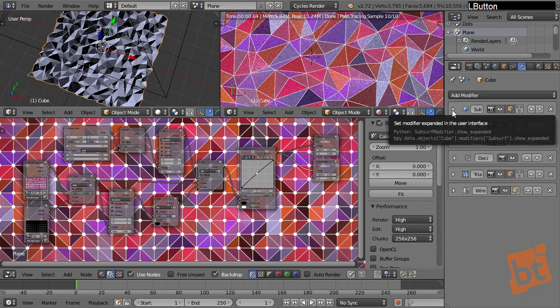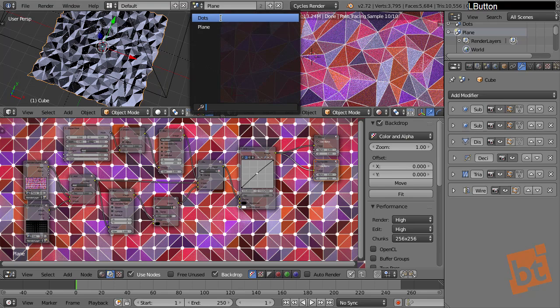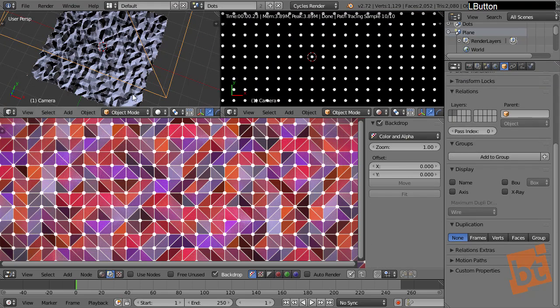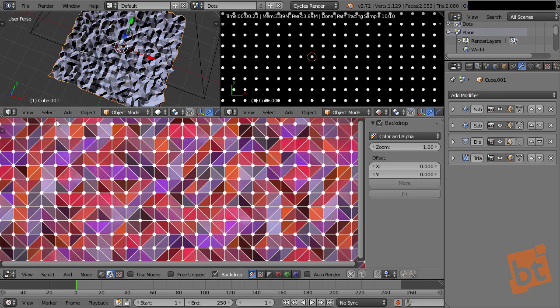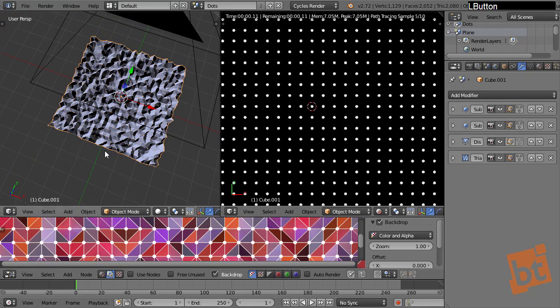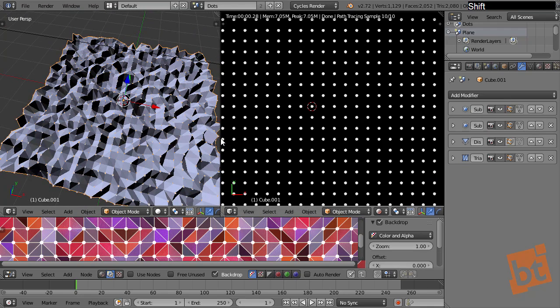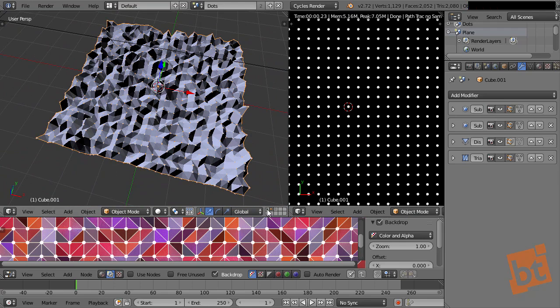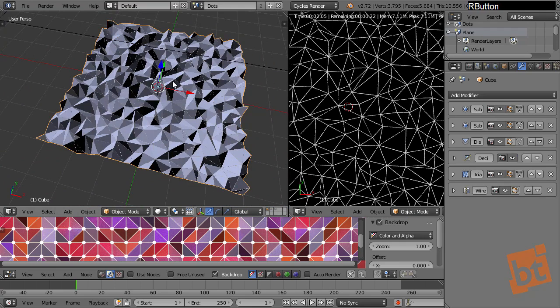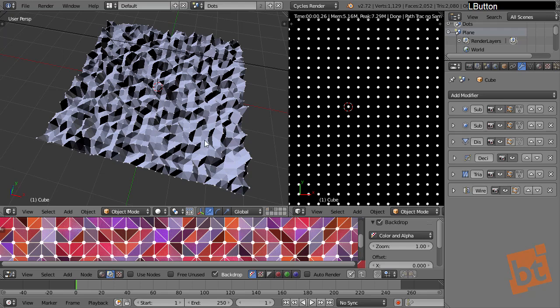And another cool thing here. Let's say we have that, and now I'm going to show you the other thing. As you can see, this is not working. The dots are not in their position. The reason is that this mesh is not taking into account the decimate modifier that we just added to the original one. If we go here, we can see that this mesh is linked to the original one, and the original has the decimate modifier, but the new one doesn't.